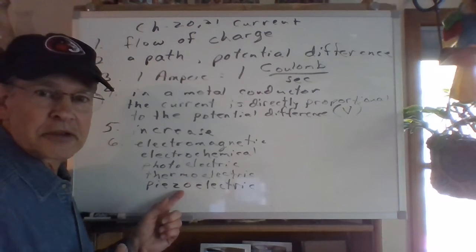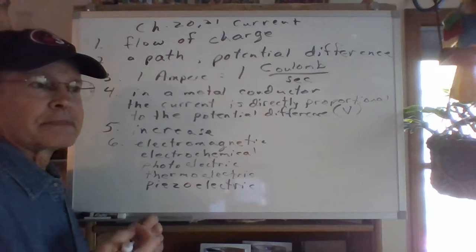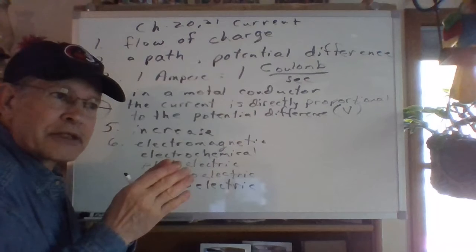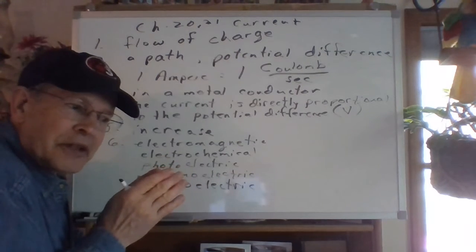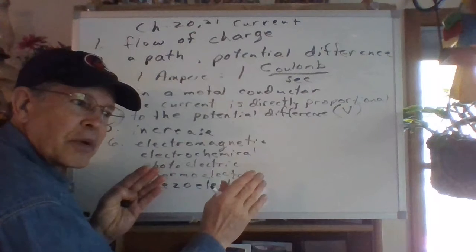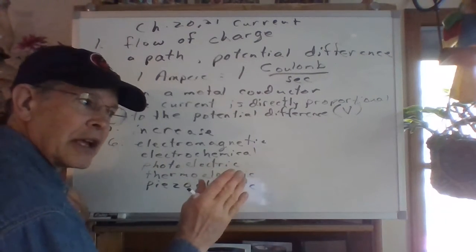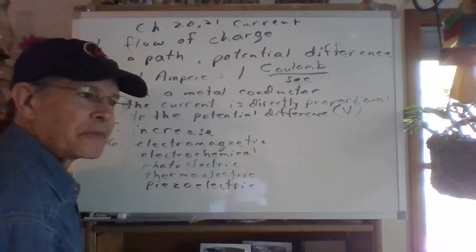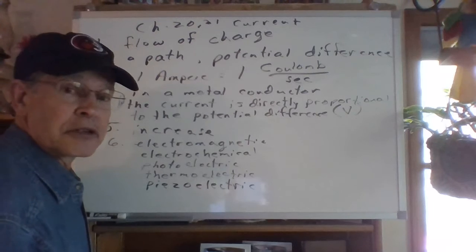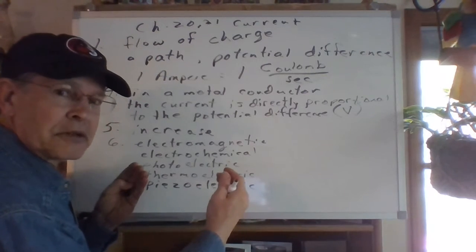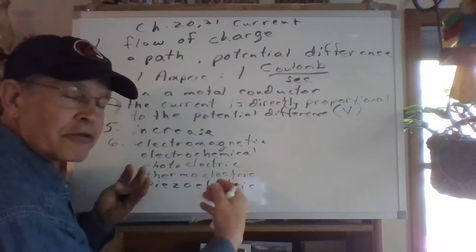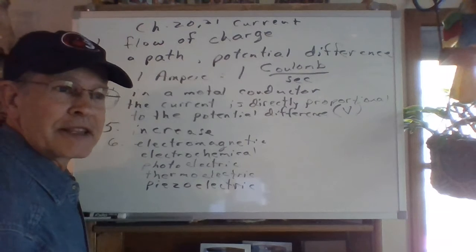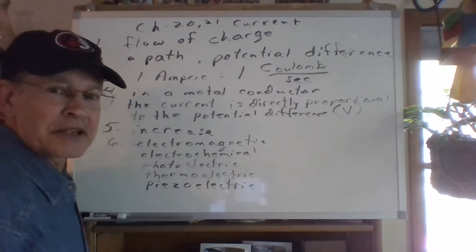But acoustic guitar pickups are typically in the bridge, and the vibration actually squeezes a little crystal. And when you squeeze on that crystal, it pushes the negative charges one way and the positive charges another way, and you create a potential difference because of that squeezing. You can use it in reverse. You can send electricity to the crystal, and you can make it move, which is common for every greeting card that sings to you. It actually has a piezoelectric crystal in it.